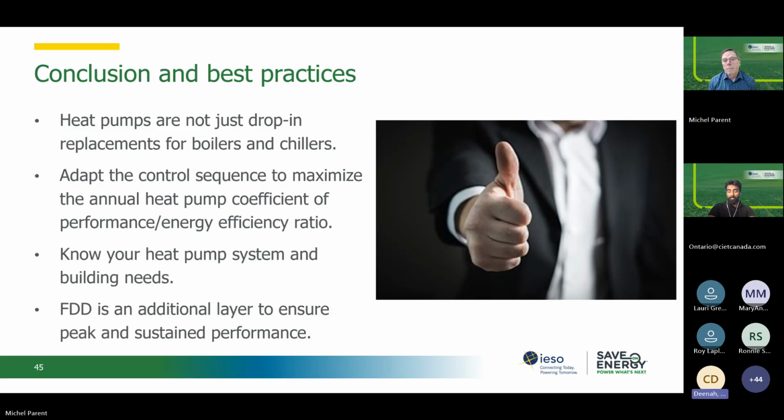Yeah, it did. And it's just something that I wanted to raise, that whenever you're looking to do those kinds of replacement, it's important also to look at your roof load capacity. And again, what came up was that there was a requirement to have a smoke detector within the duct, as part of the whole operation of the unit, in the event of a fire, for example, that it would have triggered a shutdown of that unit.